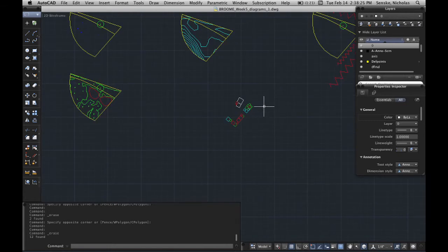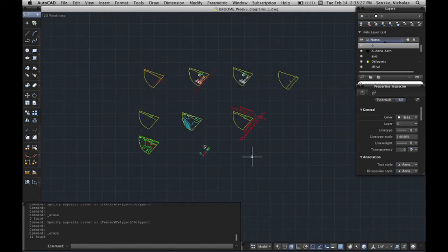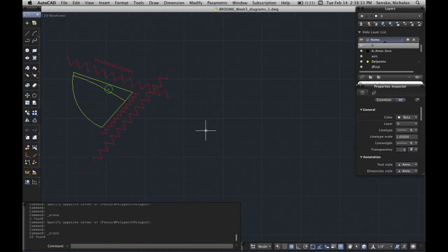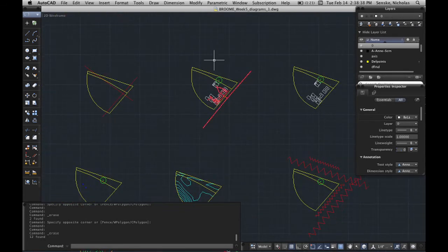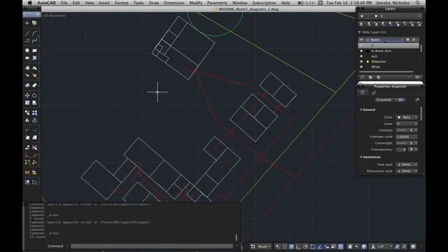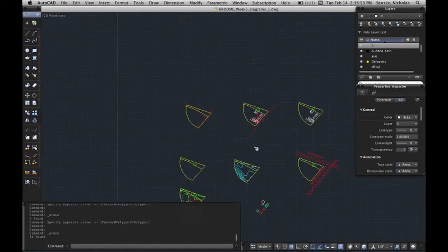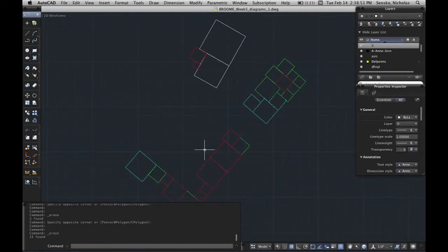So yeah, model space is the space that you're working in in AutoCAD, and in model space, as we've said, you want to draw everything at 1:1. And this is a really good example here. Doug's drawn his site, so everything here is drawn 1 inch equals 1 inch, 1 foot equals 1 foot. You don't mess with the scale here. The layout gives you the scale. Okay, you make a copy of this. You begin to develop the plan.